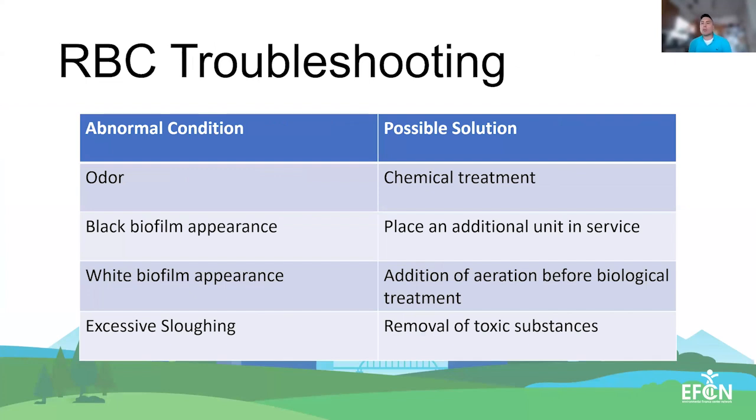Now, for troubleshooting, just like most biological treatment processes, and just like trickling filters, you want to pay attention to how much of your media is falling off, any odors that might be appearing, and then the appearance of your film. One thing to understand is that if there's odor, this may require chemical treatment.